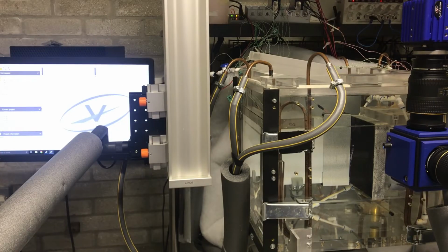So the assumption now is that the optical alignment has been performed, and that varies with different types of software or different versions of the same software, so I'm not going to show that process, just go through the manual of the appropriate software. But the very next step then is to bring the fluid seeding particles into focus, because we've kind of got close with the focus, but now we need to make sure that the actual particles that we're using are correctly in focus when they're being illuminated by the laser light sheet.